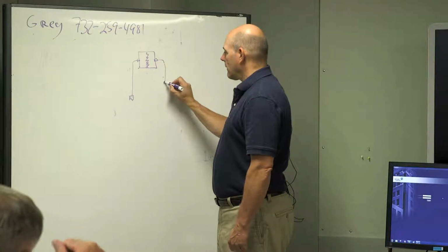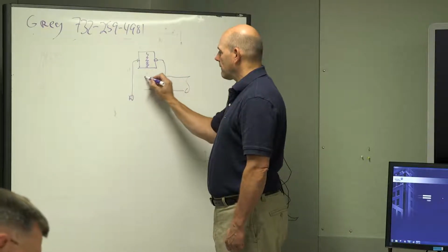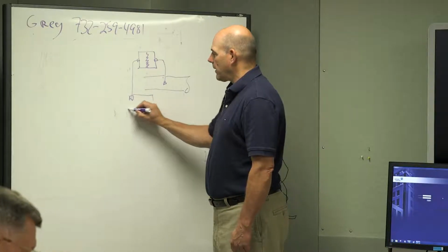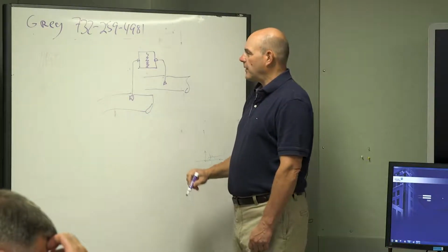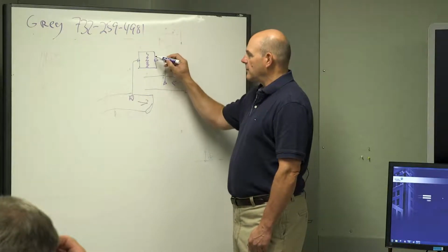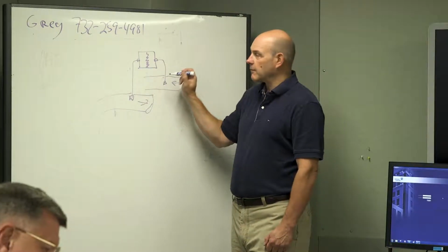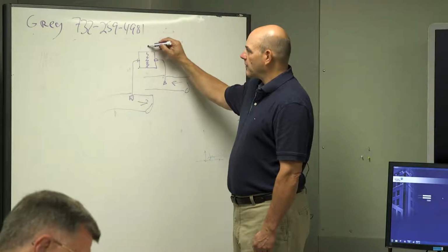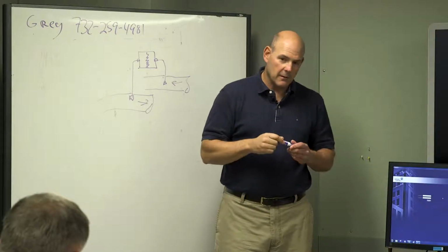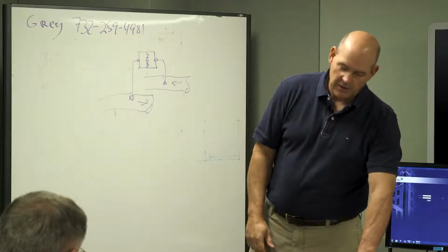All right? And why I drew this is because here's your pipe here. Here's your pipe here. Oops, I drew it backwards, but there's your pipe there. So there's a pressure coming in and a pressure coming out. This measures the differential by making this diaphragm move back and forth. So when this diaphragm moves back and forth, it sends out a signal to us. And using that, we can calculate the flow inside the pipe. So that's what that is. This will tell you your gallons of flow.